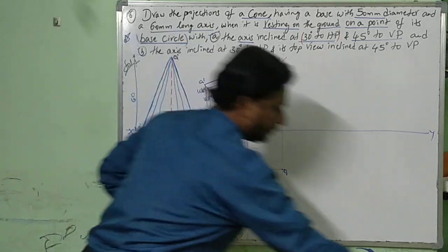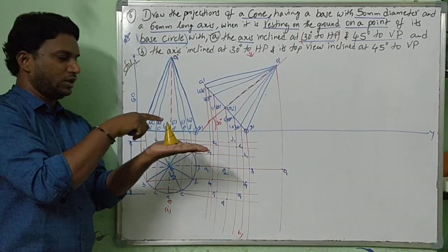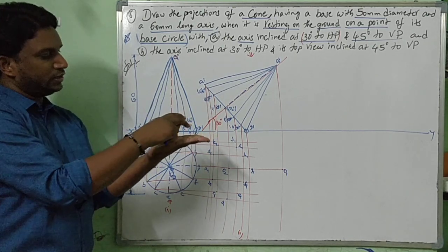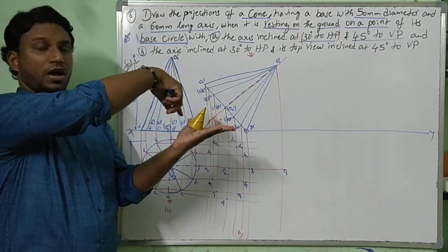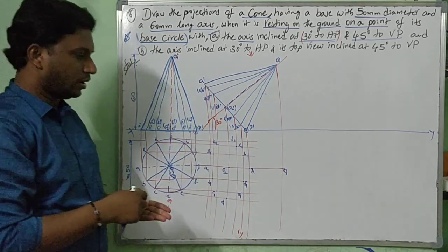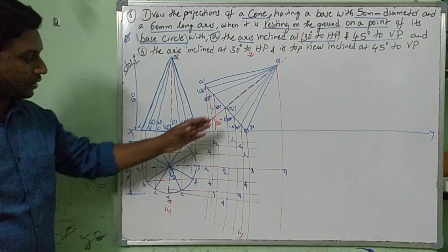Now see, when you have drawn the first stage like this, top view circle, front view boundary, inclined at 30 degrees. Now when you are looking from front, this is the thing which you have drawn here, second stage. Now when I am looking from top, I can project the boundary and at the same time I can see the curve at the left side. Now I cannot see the entire circle or entire elliptical curve thick.